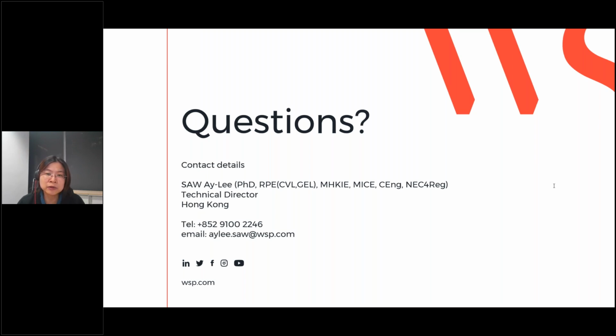So unless you are talking about large scale, because the satellite image covers about 100 kilometers. If your site is greater than a kilometer or so, it will be good, compared with using a drone, considering the cost and the requirement of frequency. But definitely these two techniques I will recommend: photogrammetry and InSAR.